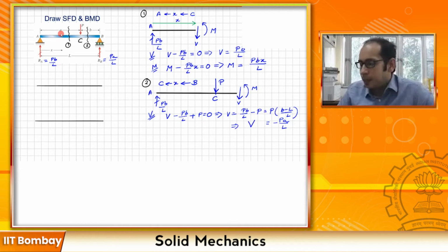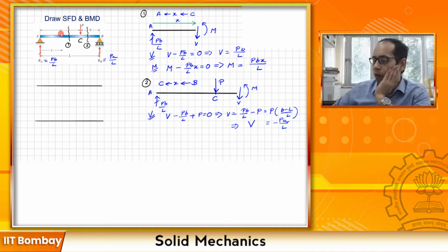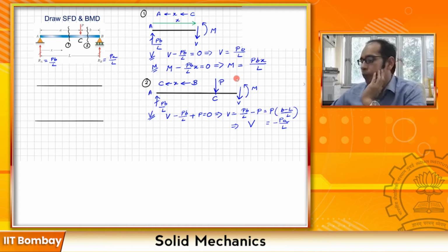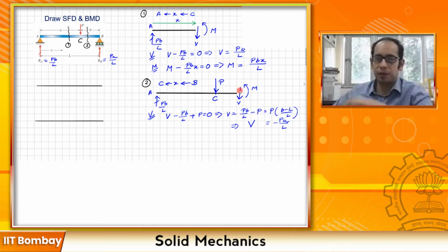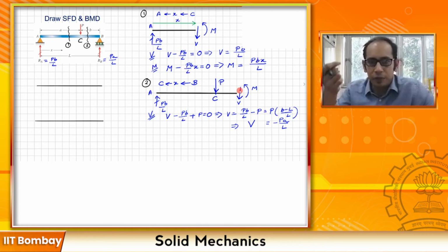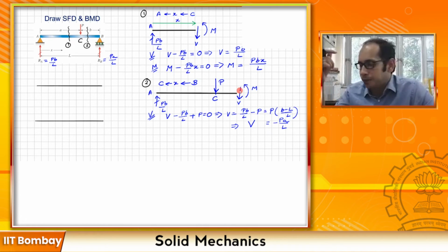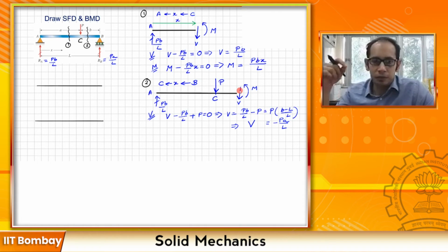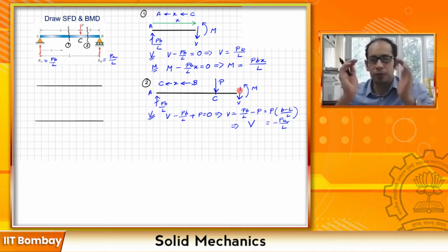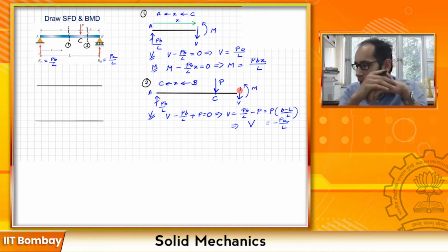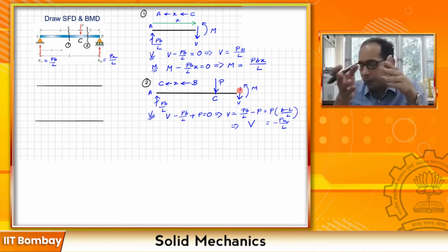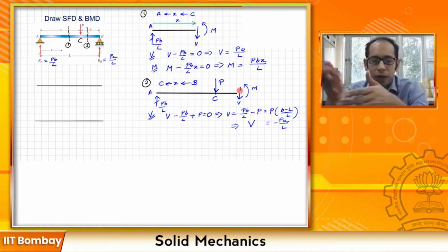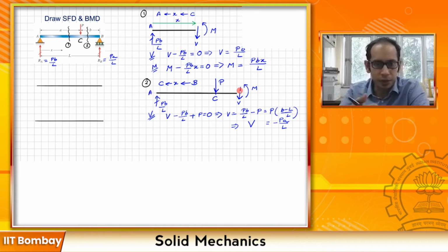Now remember that when we are marking this shear and the moment, we are marking as per our positive convention what the implication of the shear is. It rotates the element clockwise, and the moment M makes your beam into a trough. The problem will tell you, while you're solving it, whether your convention was in the right sense or not.